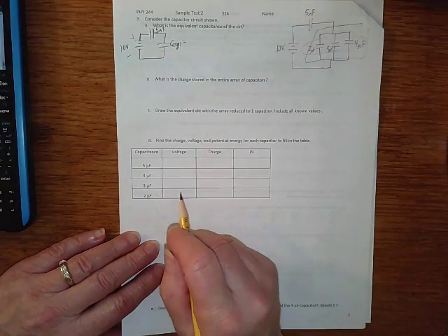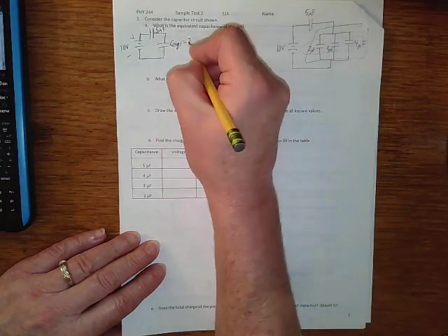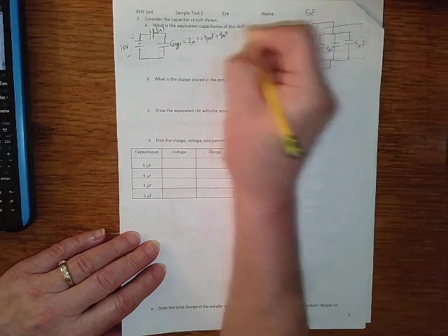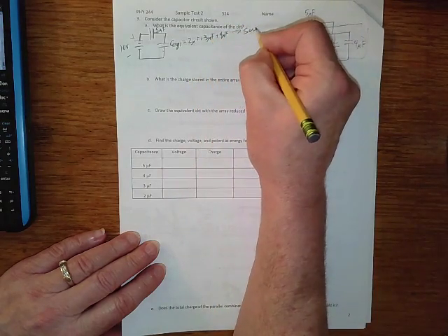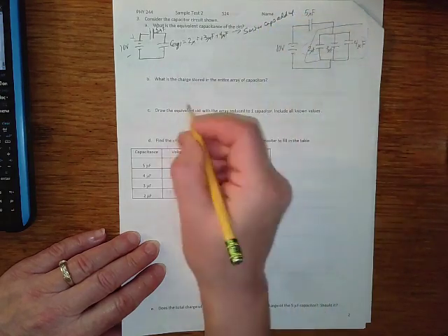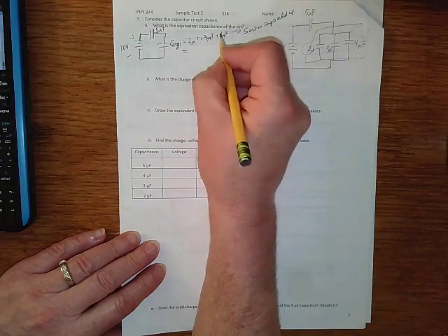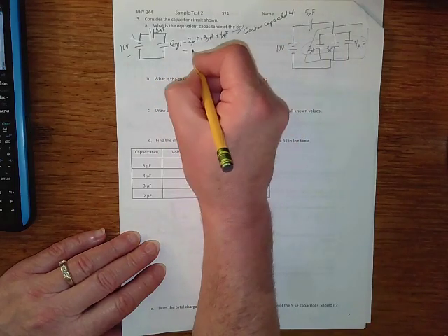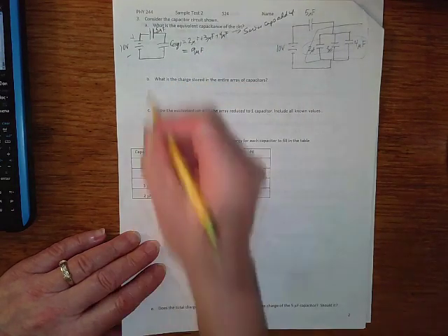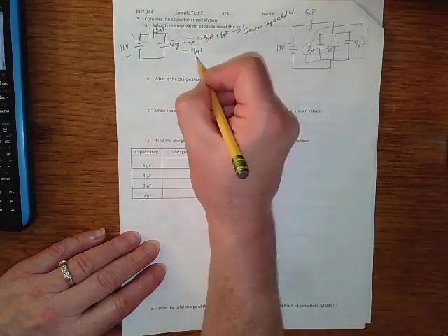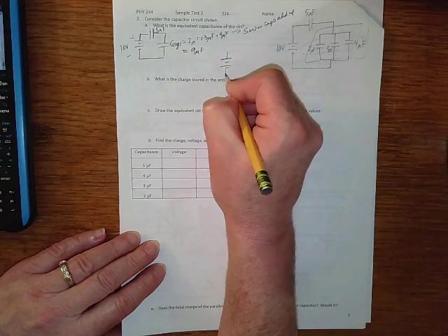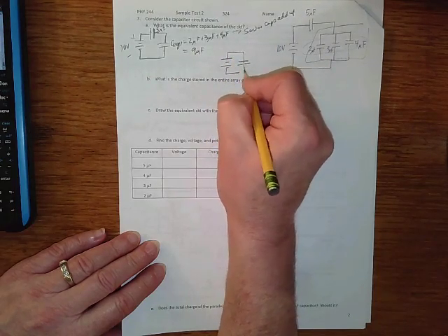And when we combine capacitors in parallel, how do we do it? We just add them up. So it's just going to be 2 microfarads plus 3 microfarads plus 4 microfarads, right? Because parallel caps add up. Alright, so C equivalent 1 is 3 plus 2 plus 3 is 5 plus 4 is 9 microfarads. Now we've got 2 capacitors in series, a 5 and a 9. So combined in series, if we do that, then we'll just have 1 capacitor left, right?